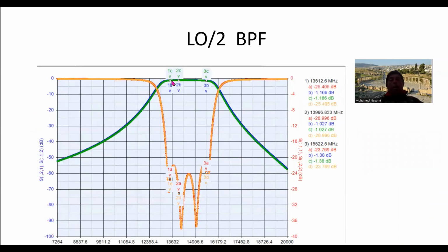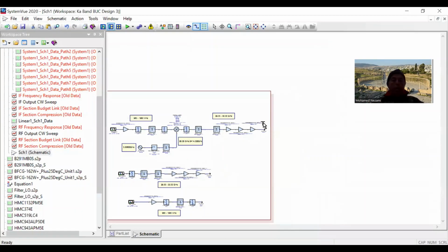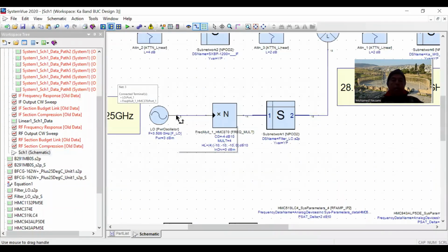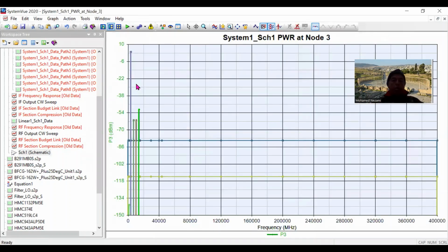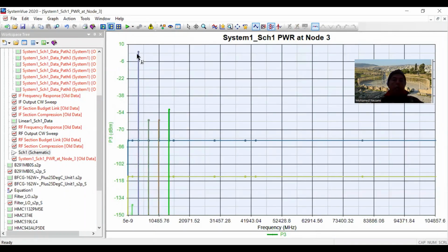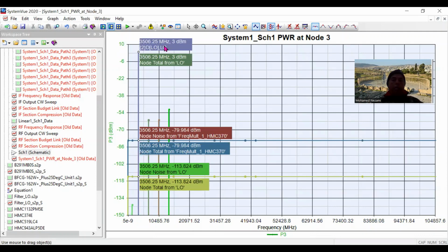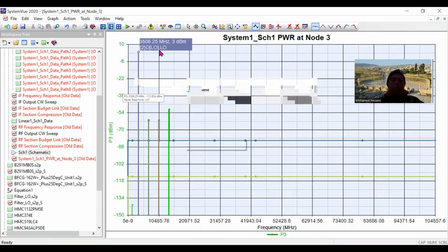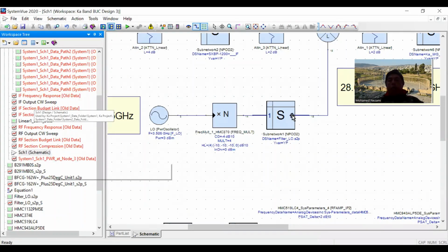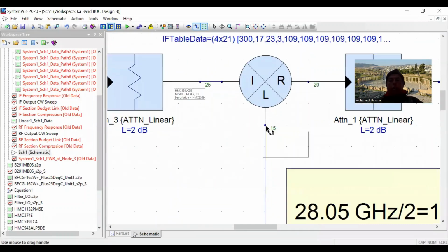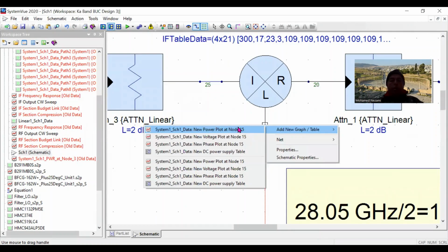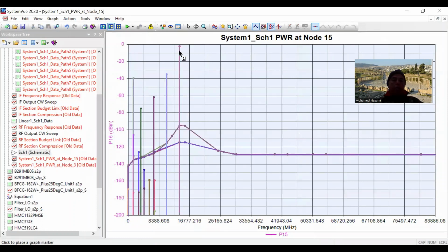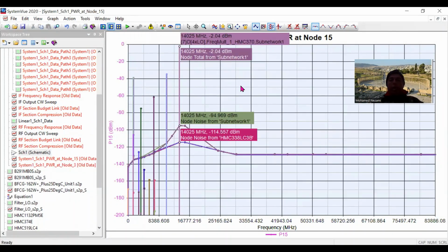So, the LO harmonic of 14 gigahertz. Remember, we start out with the LO being, let's see, it shows that. Okay, so the LO is at 3.5 gigahertz. So what we do then is we multiply that by 4 and filter it, and what we end up with at the mixer point in here with the signal level is this, of course, and that's 14 gigahertz.